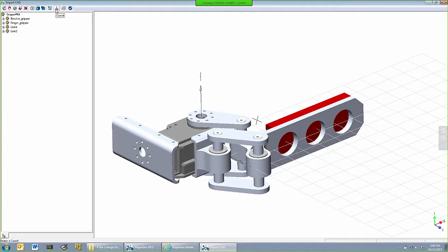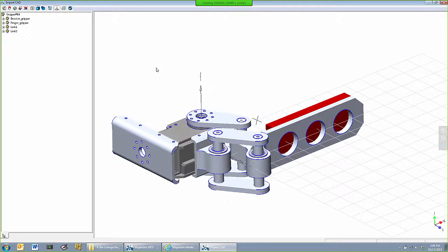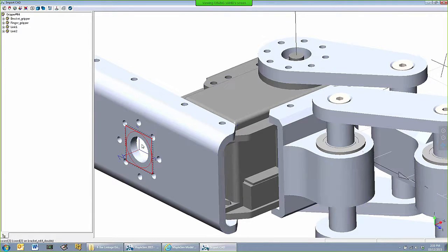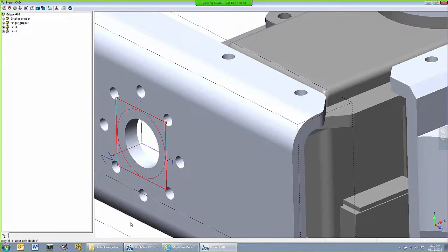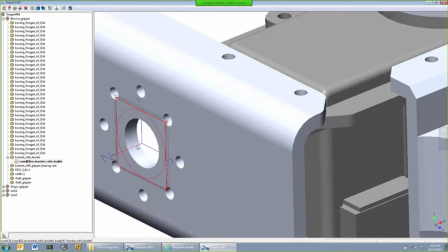By clicking on this button, it's where we add coordinates, which then translate into MapleSim as a rigid body frame. The process will look at the CAD and identify the surfaces, any lines in the model, and also any circular arc. I'm going to start with adding a coordinate to this base frame, and after creating it, it's worth noticing that each coordinate will come with a z-axis, x and y, and orientation that are taken from the surface or object that it is attached to.